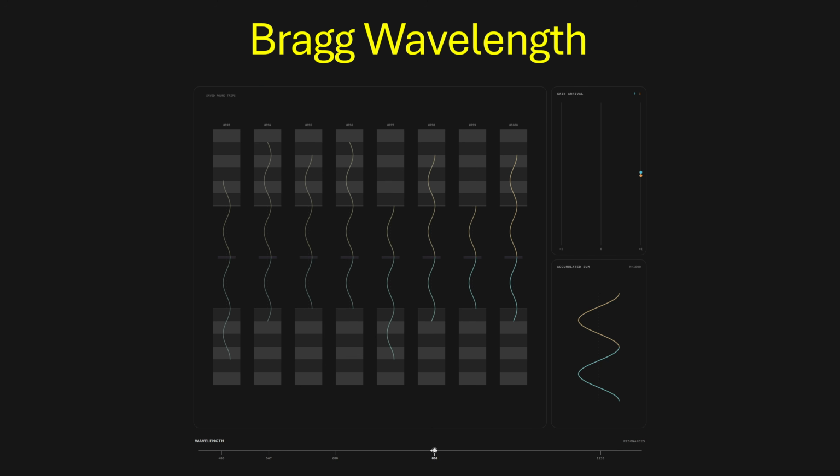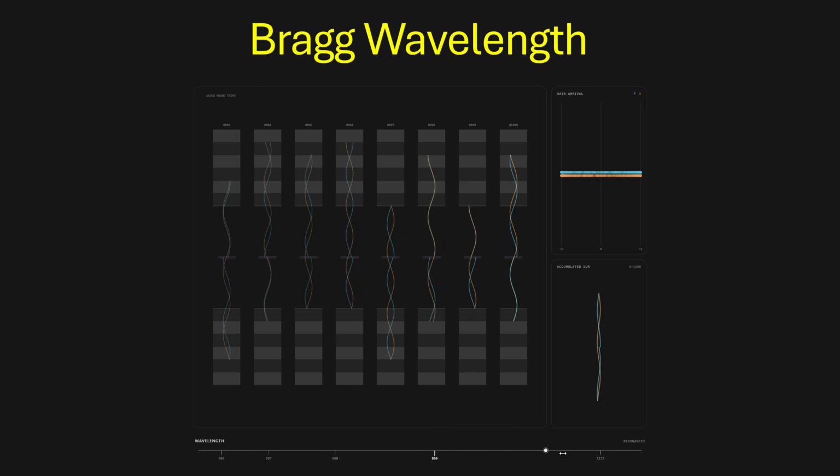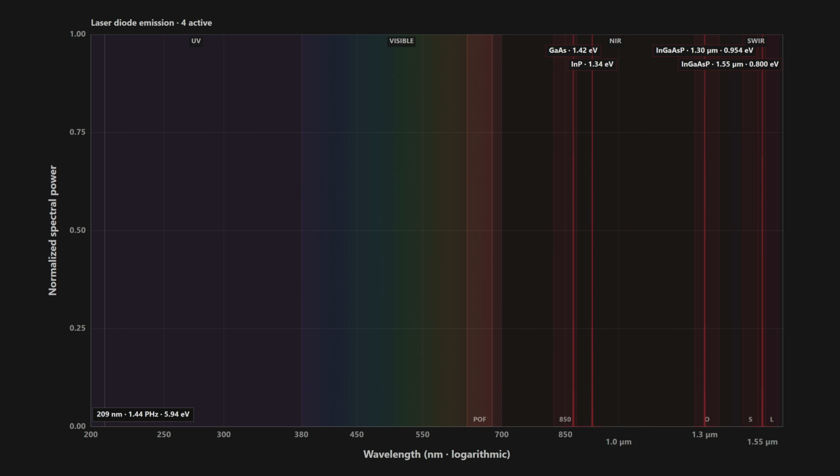For other wavelengths, since there is a phase offset depending on which layer they reflect at, there is a destructive interference in the reflective wave. In other words, these wavelengths mostly pass through the Bragg reflector without reflecting, and this is another layer of wavelength selection. This system results in a narrow wavelength and frequency range, and this is called the line width in the context of lasers. However, the line width and other performance metrics of VCSELs are poor compared to other edge-emitting laser diodes.